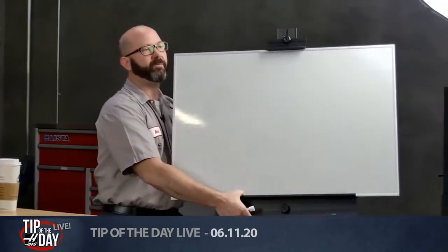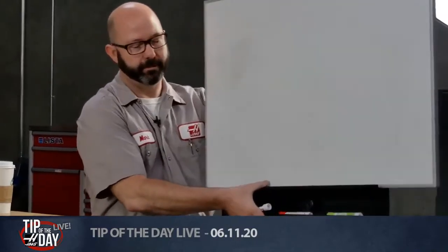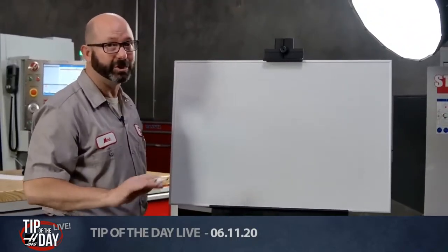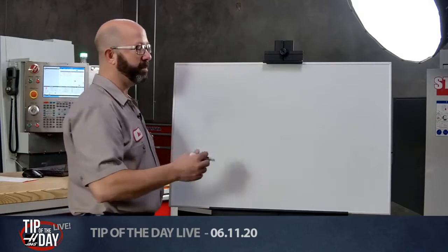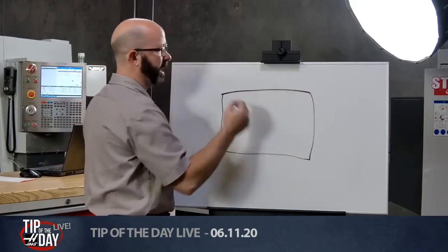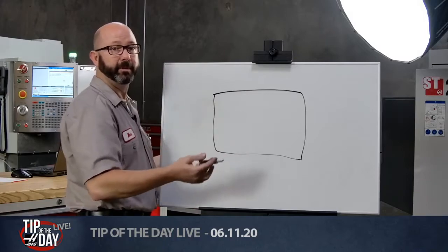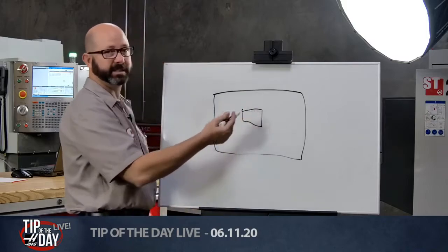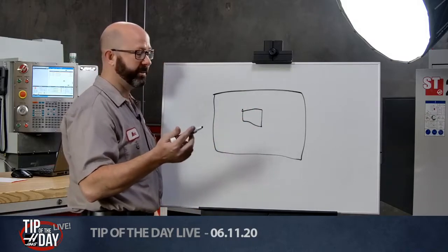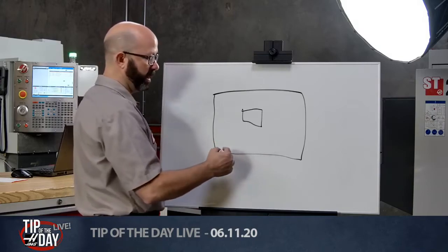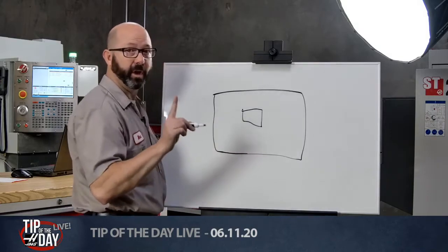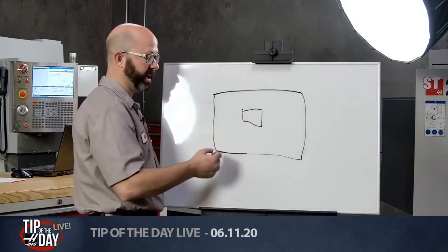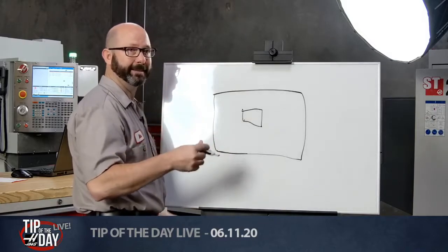And so if I was going to do that exact same pocket with a G150 cycle, G150 is super easy, basic. But when you add a boss to the middle, if I wanted to create this, then I define my 4 points. That becomes my perimeter in the G150 cycle. If you added in another boss that sticks up that you want to avoid in the middle of the G150, you have to be clever with the way you do this. You can only define one perimeter, one contour in the G150 cycle. You can't define this one and then an avoid cycle. You only have one defining contour.